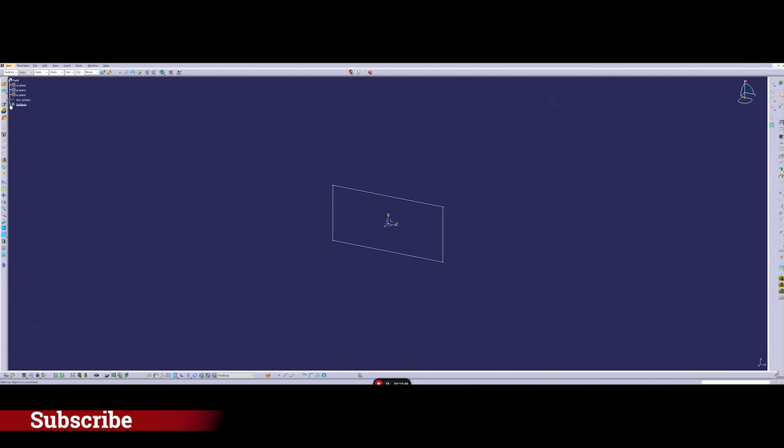On the left side, you will see the tree. This is the tree with a lot of information that concerns my design. Whatever I do is stored inside my part body. From the tree, you can do whatever you want. By pressing Control and scrolling up, you see that I can have a bigger tree with bigger letters, to make it easier visually. So whatever I design here is stored in my workbench, in my tree.